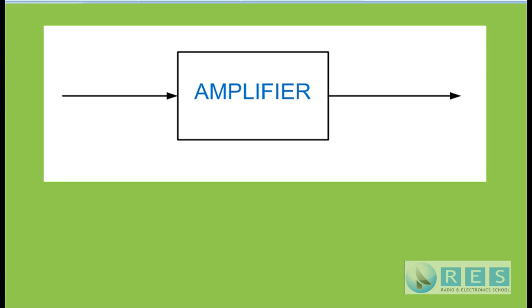So we've learned that amplifiers, broadly speaking, are broken up into two categories. Linear amplifiers, ones that amplify without any distortion. Whatever you give them, they just simply make larger and give us more power. So a linear amplifier would be used to increase the signal strength of a single sideband signal. Nonlinear amplifiers distort whatever we give them to amplify, and we'll be learning shortly why that distortion can be useful to us.